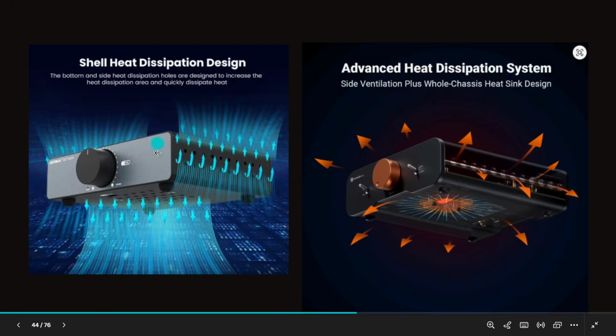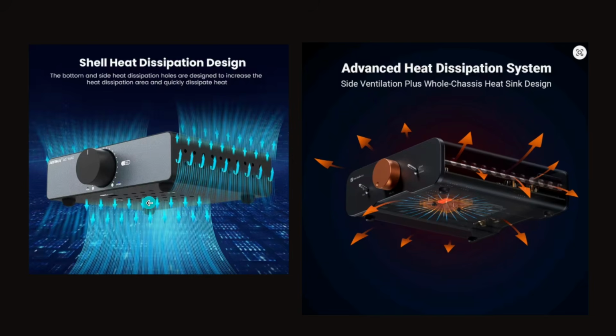And here as well, heat is not distributing in this way. All heat from the bottom, where you have that chip, will go up, and all this enclosure will be hot as hell. And air will not go out of those small holes. There is not a sufficient chimney, or not sufficient height. This particular design cools only by spreading heat through the enclosure. There is no airflow. And how to make an airflow? You just need to turn it into a vertical position.